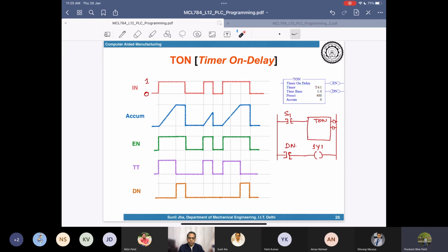So that is the way you can use a proximity sensor, a PIR sensor, that's a passive infrared sensor, to detect the presence of a person. And based on that input, you will be running the fan. So it will not be starting immediately. Otherwise, what will happen? If the person goes in and out 3 times in a minute or so, then the fan will turn on and off, on and off, on and off. This cycle will continue.